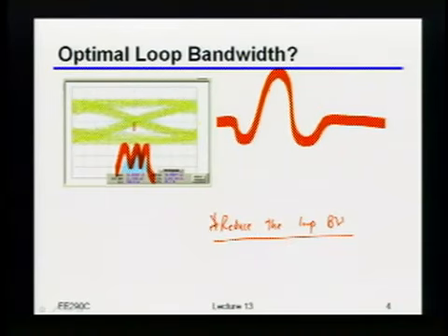Loop bandwidth can't be equal to, I mean, it's always slower than the data. Ah, okay, so that's actually one great answer. To do what I just described, if on this cycle I saw I was off by 10 picoseconds, within half a bit period I would have to shift my sampling position also by 10 picoseconds, right? And so what Igor is basically saying is, come on, there's no way you can build a clock and data recovery loop that would respond that quickly. That is actually pretty much correct. That is basically the crux of the issue.